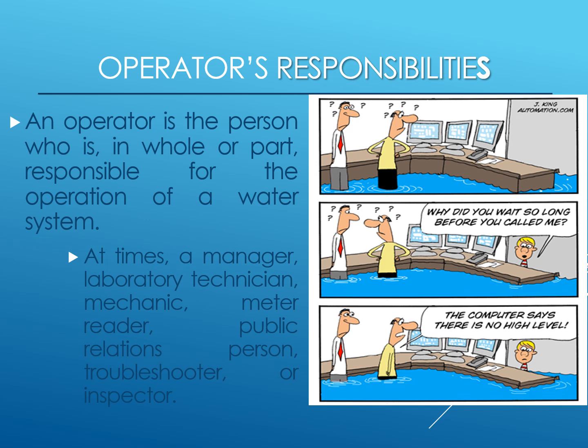Overseeing the water treatment process includes the coagulation and sedimentation processes, where the suspension of solids and other impurities from the water are removed. The filtration process, where the filters remove remaining particles, making the water clear. The disinfection process, where chemicals like chlorine are added to kill the bacteria and other microorganisms. And then also, in some instances, fluoridation, where fluoride is added to the water to help prevent tooth decay.